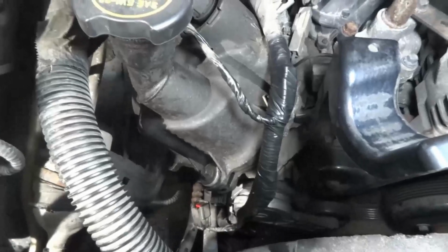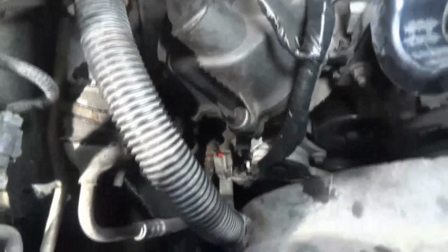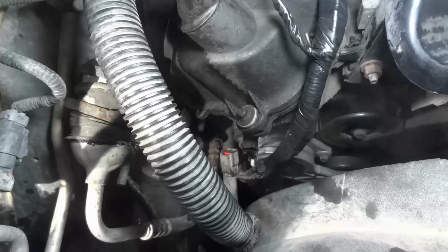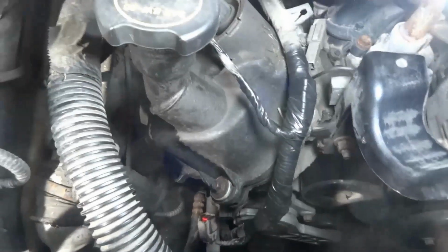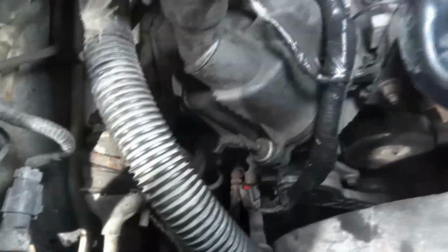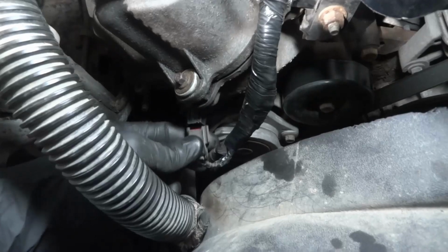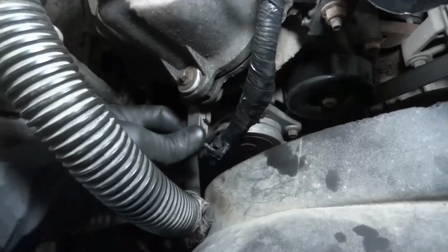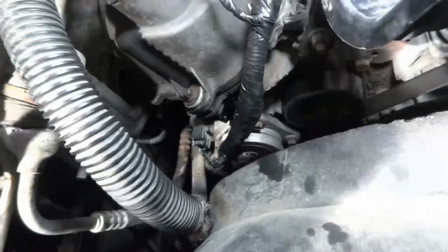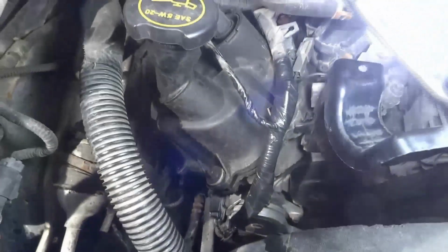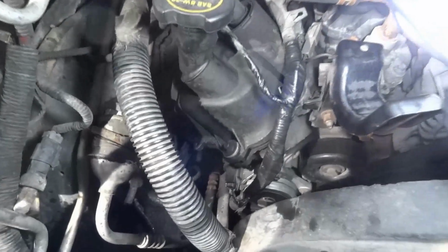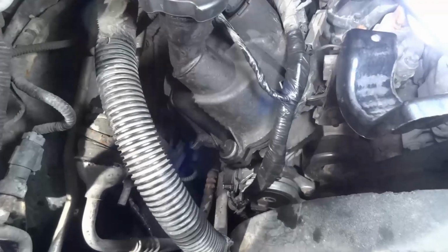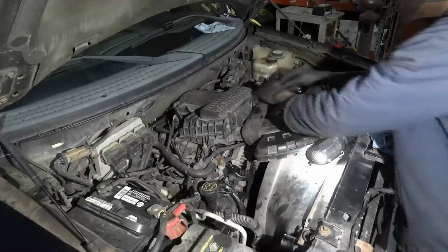Here is the wiring harness that I have taped up. So we fixed the wire, everything looks good. Okay, so the camshaft sensor wire is taped up against this main harness over here, so we should be good to go with this. So now I'm going to connect the sensor, so we're gonna plug it back in, so right there. All right, okay, so this is good. So now let's reinstall the upper radiator hose, and then we're gonna go inside the vehicle to start the engine.